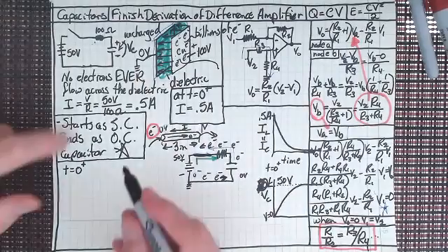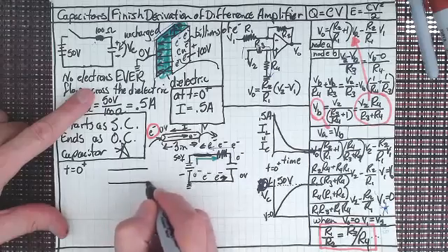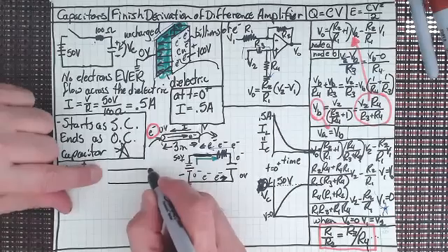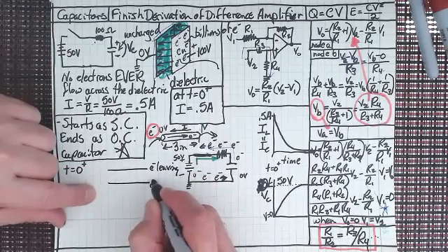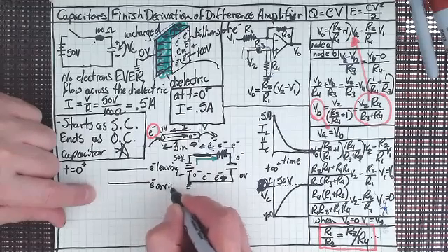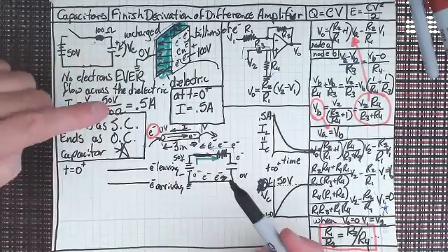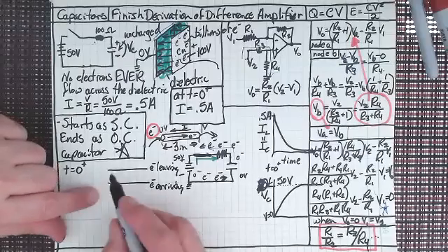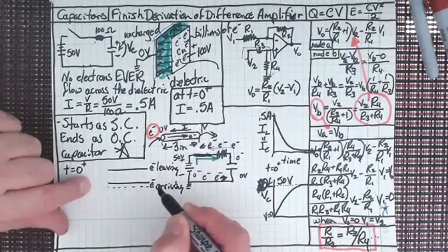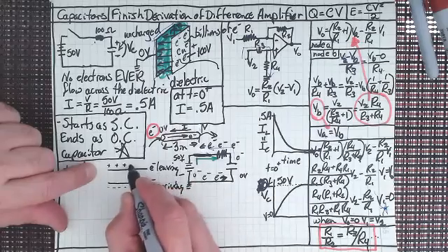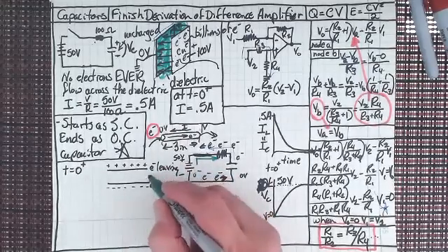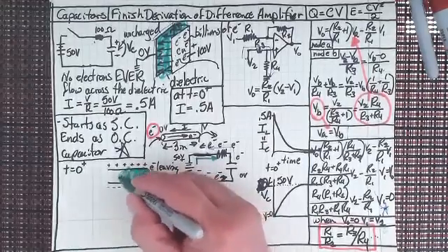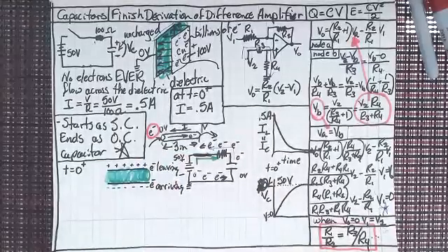If we look at what's going on inside, let's blow that capacitor up a little bit and look at it. So the electrons are leaving this side, and the electrons are arriving at this side. So I'm going to have a negative charge over on this side eventually, and I'm going to have a positive charge over here because all the electrons left here. So all that's left is the positive charge, and on this side, all that's left is the negative charge. Has any electron ever crossed the dielectric insulator boundary in between the two? No, it never has. It's never done that.